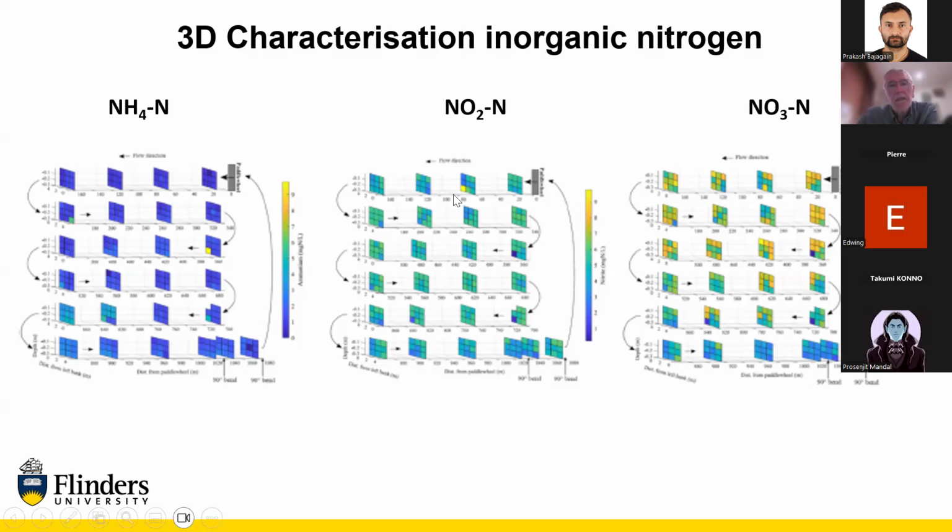And what we see here is, yep, we've got reasonable amounts of nitrite and nitrate in the system. So it's oxidizing. But what's also interesting is this question here. When we look at ammonia, nitrate, we start to see lower levels of nitrate in the final channel before it goes back to the paddle wheel. And one of the questions we have here is whether the bacteria are somehow being challenged for one of the substrates.